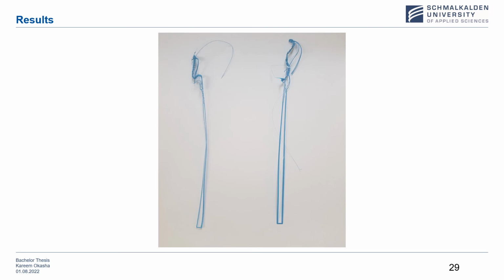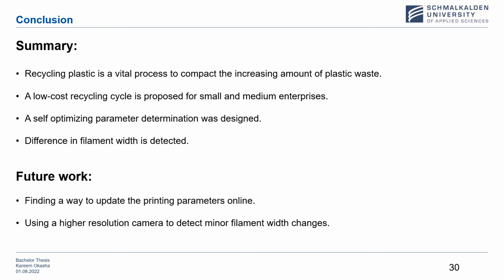And here are test prints when trying to test for under extrusion by using lower temperatures. However, the prints failed due to the low temperature used. And in our case, we need to use higher temperature differences in order to induce higher variation in the filament width in order to be able to capture it with our low resolution camera.